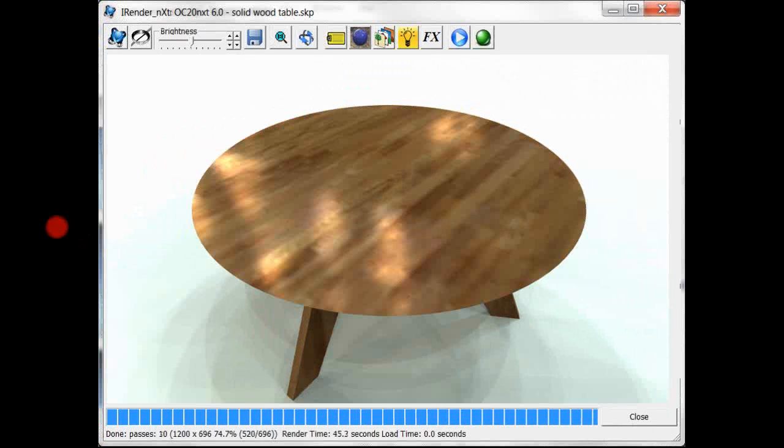So now I have a more polished looking tabletop. Now again, this is a rendering that's created with Studio High Dynamic Lighting. Just think of that as taking it to the photographer's studio. I have a really nice wood surface, and now I've given it some reflections. The biggest benefit is that with Studio High Dynamic Lighting and reflections turned on, I'm able to sample this wood material in direct light, in filtered light, and then also in shadow.